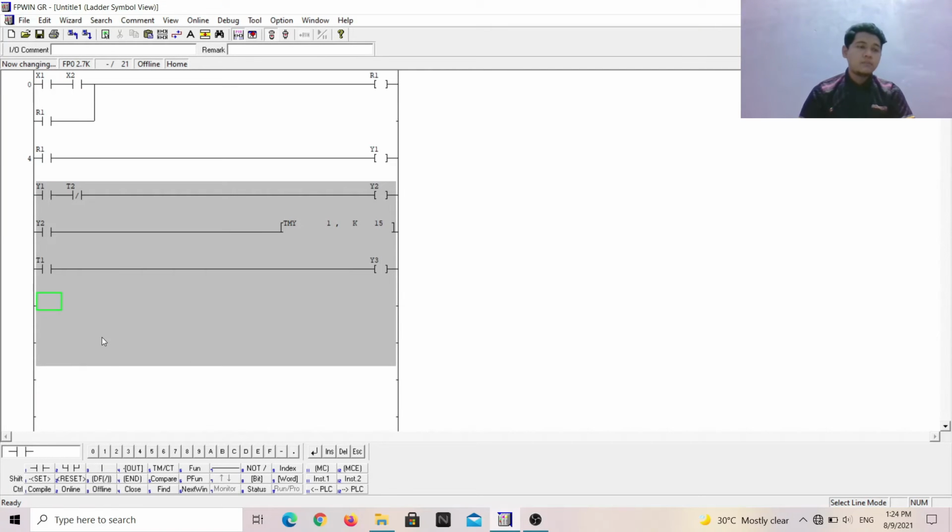Okay, now I will explain about the next process. The next process is the filtered water spray. For the start button it is Y3, and then timer 2 with a duration of 25 seconds. Then we put T2, because we want to repeat this process for 2 times.